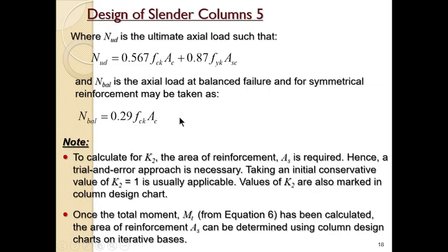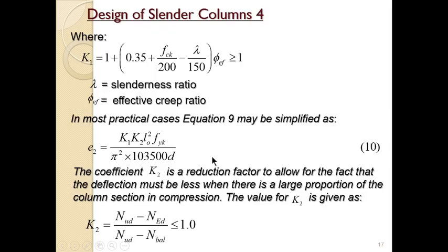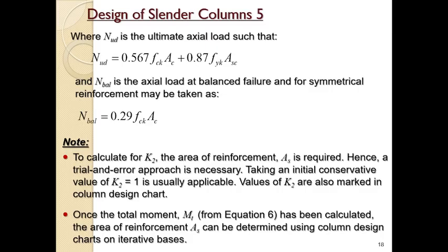But the emphasis is this is where we might start making a little sense. To calculate for EK2, the area of reinforcement is required because you need to calculate this M bar and NUD. You can see this area of concrete. Let's look at where the area of reinforcement is required.